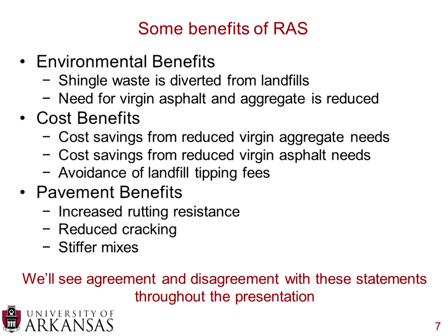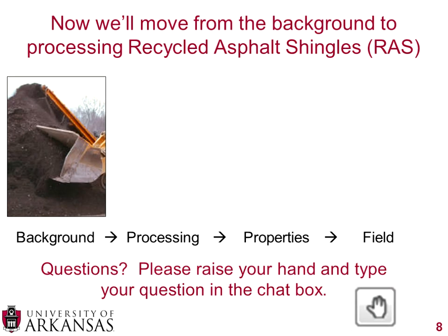And then also there's the theory that you have some pavement benefits too. So from what I reviewed, some people say it increased rutting resistance and reduced cracking. Overall, I never saw any argument saying you did not get a stiffer mixture. So you will certainly get a stiffer mixture using RAS. However, the rutting resistance and the cracking, those are things that I've heard going both ways. So we'll see agreements and disagreements with some of these statements throughout the rest of the presentation.